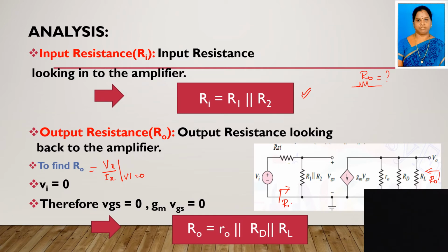So instead, another method to calculate the resistance is to apply a known voltage. For example, if you apply 5 volts here, some current flows, right? That current can be measured by an ammeter. So the current flowing through the ammeter, we can measure that as Ix.